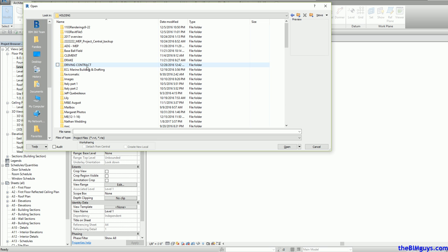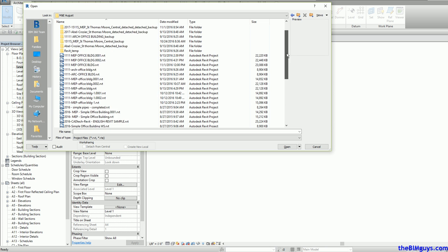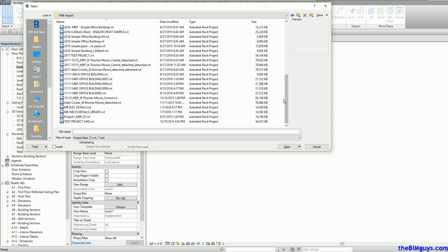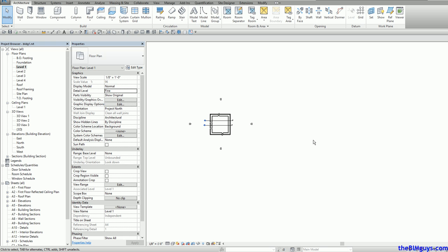All right, some MEP stuff in here. But when we open this up, can you bring pipe and wire at the same time, or no? Wire is diagrammatical. It's not a true wire. You just calculate how many feet. You can put wire parts in. Let me show you how to get the pipes in, and we'll go to that.